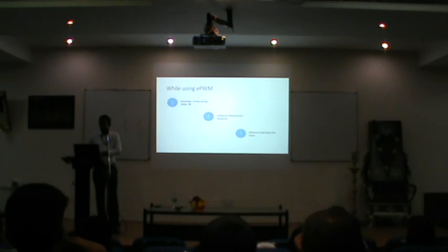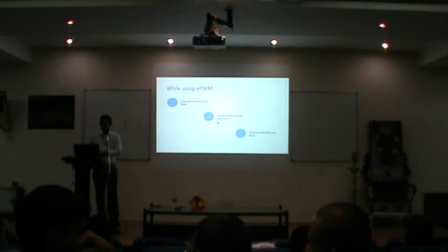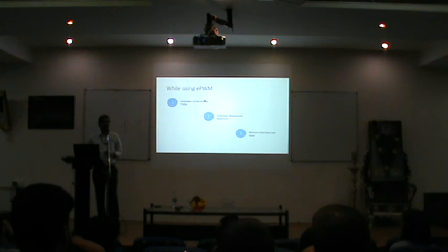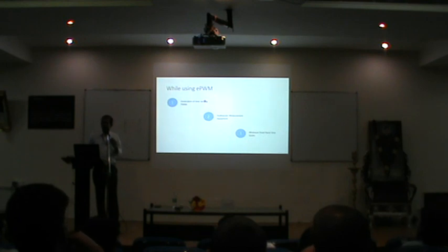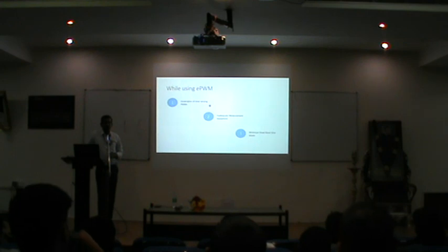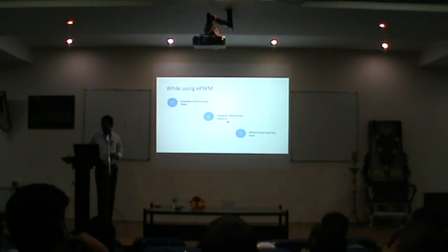I don't know whether these things will make sense to you. While generating a PWM and testing these things, it is absolutely essential that you have proper measurement equipment. Generally we use low-cost oscilloscopes, so you will have issues when viewing time-varying signals. Unless we have proper measurement equipment, we shouldn't conclude that our design and implementation is not correct. That is one point to see, inadequate measurement.